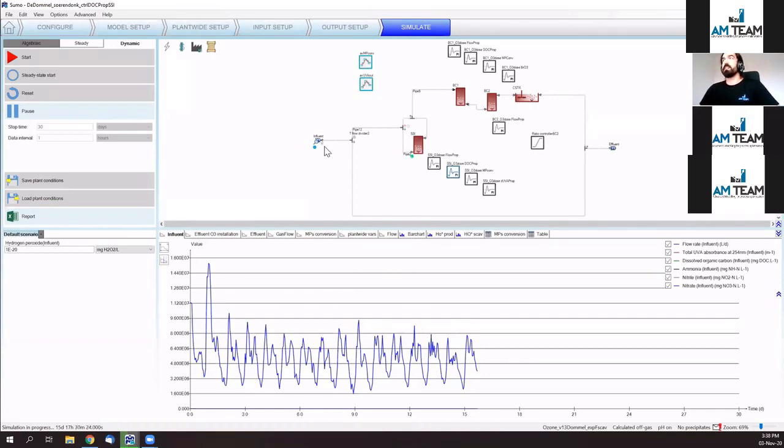What you see here, the effluent wastewater from the treatment plant is arriving to a split, which is a bypass where the high peaks in outflow are bypassed into the overall plant effluent. But most of the flow is directed to our ozone installation, which is sized to treat most of the water flow exiting the wastewater treatment plant.